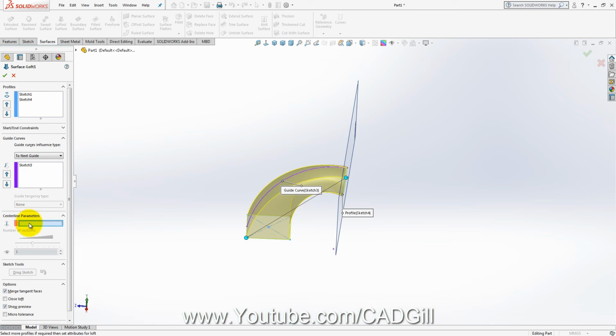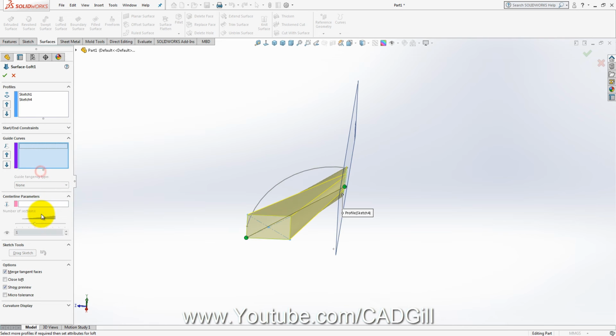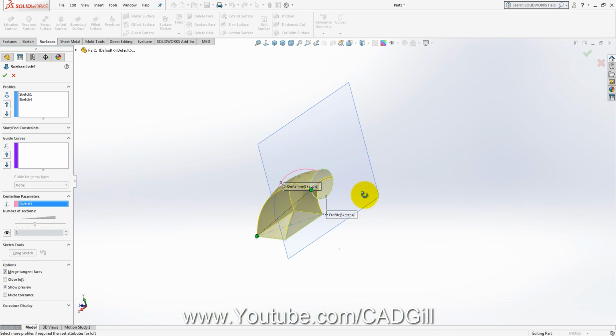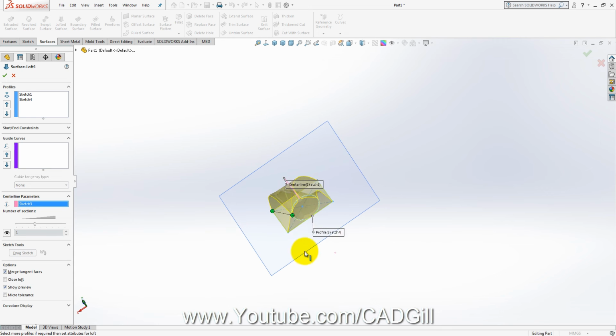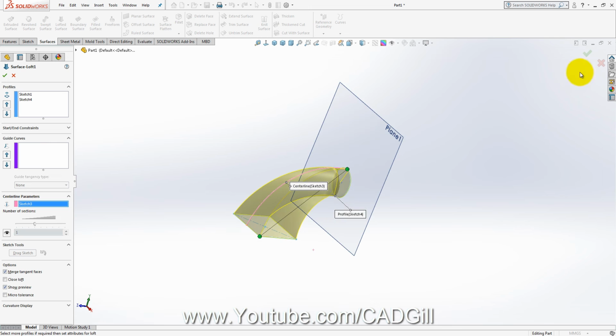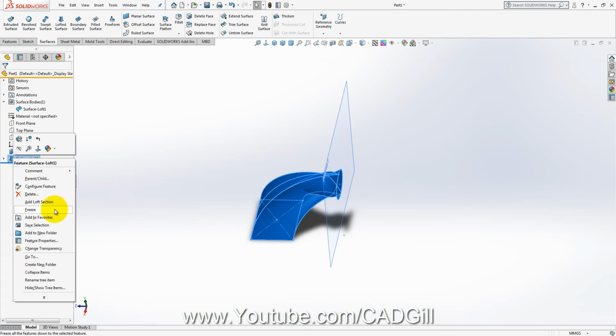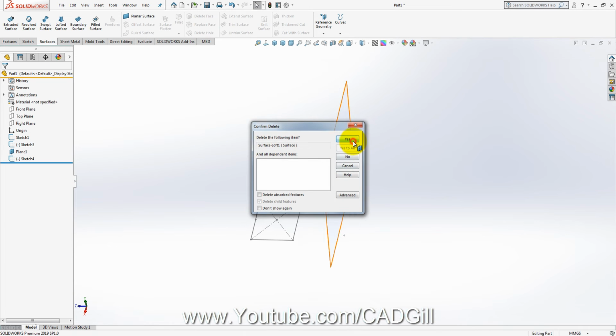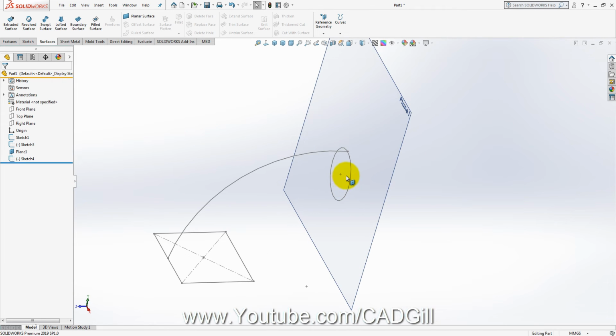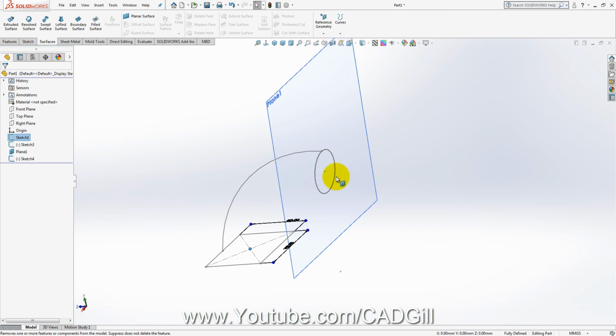You could have also used this as a centerline parameter, but the results are a little bit different. Okay. So that was actually a guide curve, because for centerline you needed to have created a sketch from this point to this point, the centers for the profile.